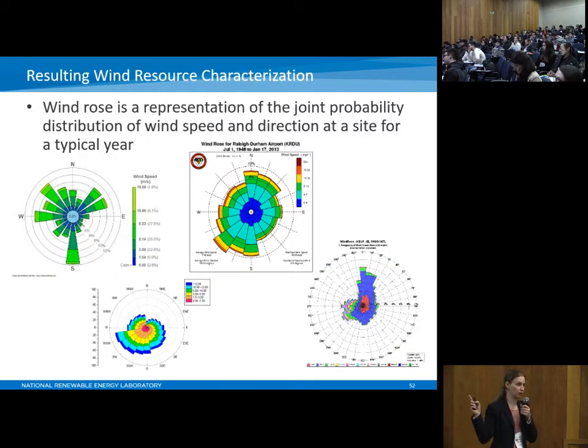These are wind roses, and I just pulled a random selection of these off the web. They vary a lot all over the world. Different sites have very different looking wind roses. These don't look anything alike, do they? No, not really. You have this one here, which has a bimodal distribution. You have a really strong prominent direction from the north, and then a second mode here coming from the west. And what these colors represent on the wind roses are frequencies of different wind speeds. And then these are different direction bins.